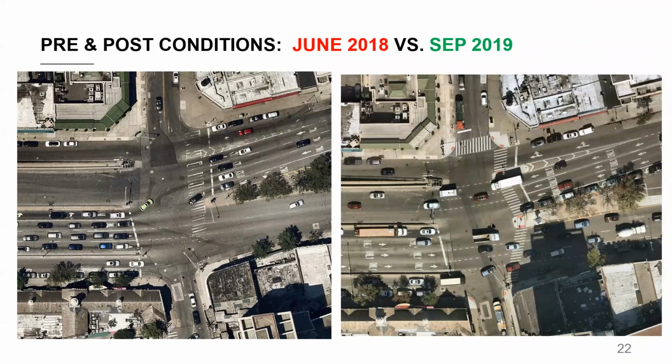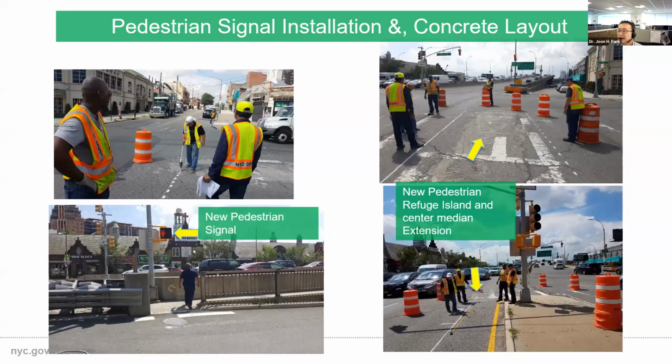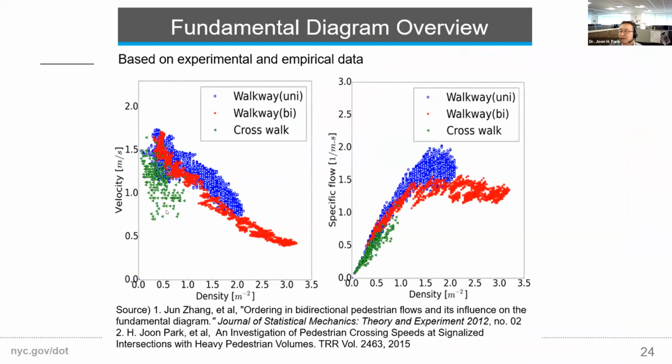Yep. Yeah, because once you consider all the intersections, I'm going to answer the first question about speed. We have research on this. Actually, we got it in feet per second. Usually my colleagues study walkways; we study crosswalks. This is a range for a very heavy crosswalk in a busy area in those locations. So when you see that over here, we use 3 feet per second for the elderly people and the school area. So technically that range is covered. New York City DOT has a policy of 3 feet per second, which is about 0.9 meter, a little bit higher. That is how we usually prioritize the pedestrian.